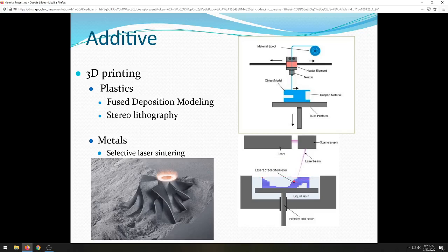This process is being reversed right now. You can actually buy a liquid 3D printer where the light source is in the bottom. It's basically a really bright LCD screen, and then the platform goes up. So the platform starts on the bottom and then moves up and pulls the object out as it's built from the bottom. Those are really good for fine details.